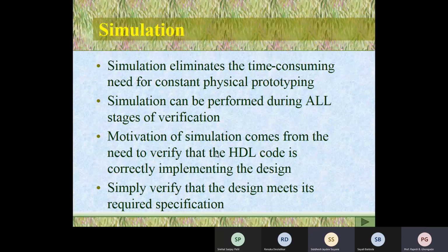No. This is only a very small part of the entire specification. Please remember that whenever you start with design, you should start with the specification. Now, specification in case of a linear power supply: there are roughly three classes of specifications. Input specifications, then the output specifications, and the ambient specifications.